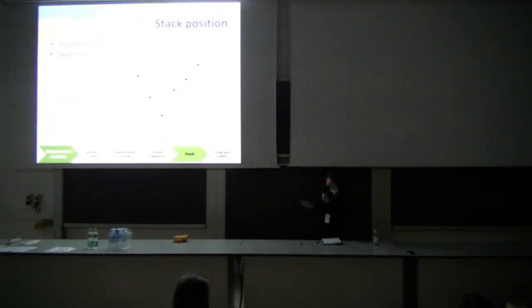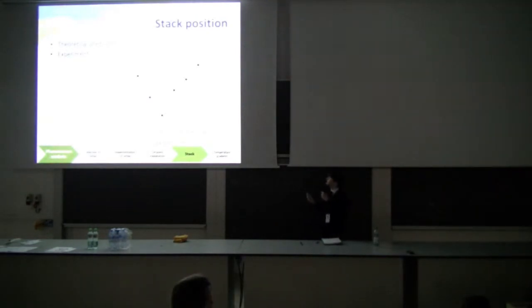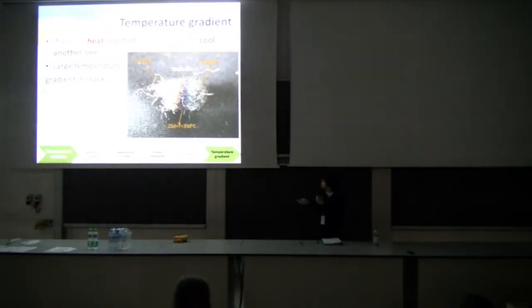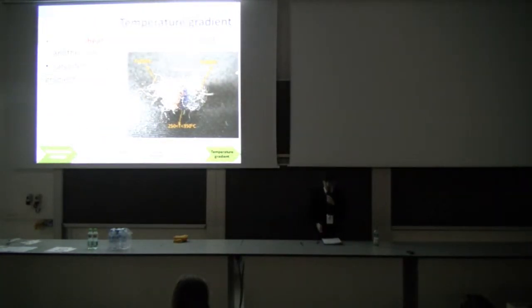Also, we tried to study the optimal stack position. Both from theoretical and experimental points of view, we discovered that the central part of the tube is the most optimal stack position. Also, as you understand, we must maintain the temperature gradient across the stack, because one part of it must heat air and another part must cool it.